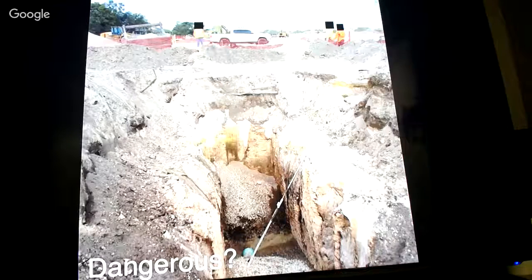Now, make it very simple, very easy. Trenches, at 4 feet, you got to have egress, whether that's a ladder or a low sloped ramp going up out of the actual trench. At 5 feet, you have to have cave-in protection. Now, these are no ands, ifs, or buts. You have to have it in place. If you don't have it in place, you're not within compliance. Now, there's a difference between being in compliance and also being dangerous.